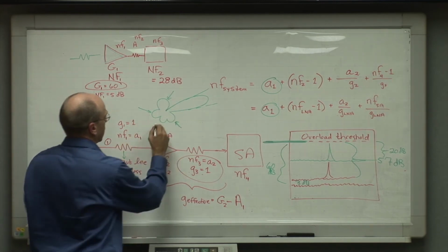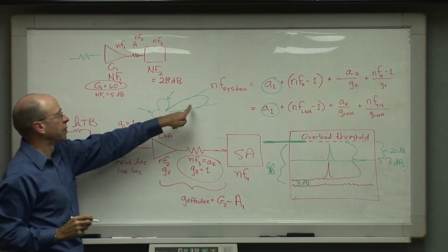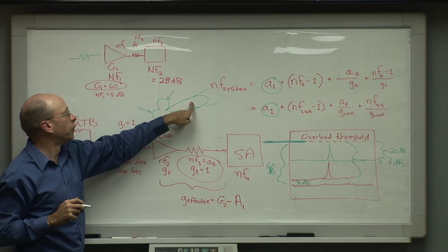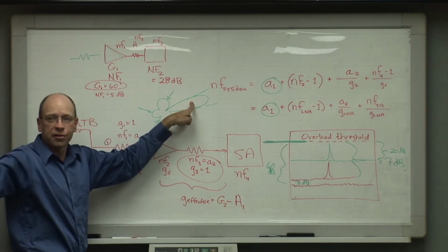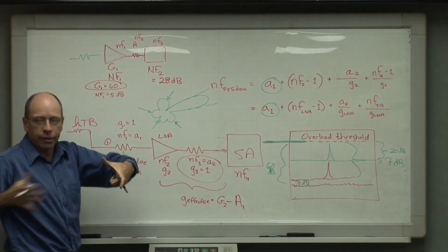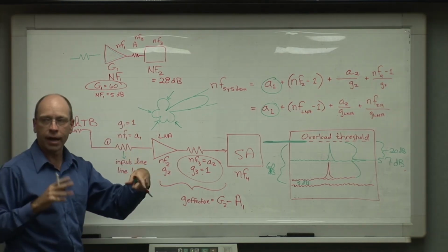So you don't collect any more energy from a distributed background source in a highly directive beam if the source is distributed across the sky or across a wide angular distance than if you were using an omnidirectional antenna that got energy equally from all directions.